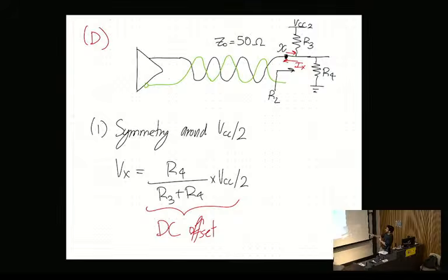And so if I use superposition, what do I do to VCC2? Ground it. So now I'm just looking at what is IX. So if the top is ground, what's the relationship between R3 and R4? Parallel. So what would be the voltage at Vx then? Exactly. So Ix would be the current there, just multiplied by the parallel combination between R3 and R4.